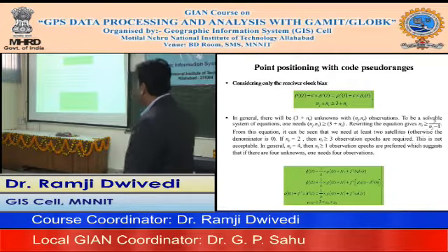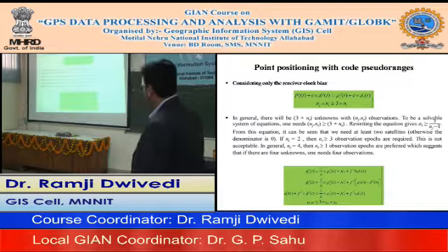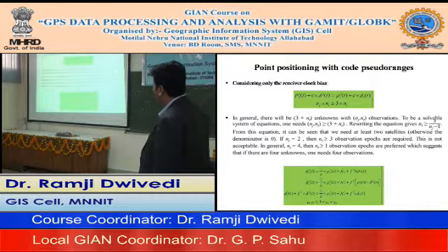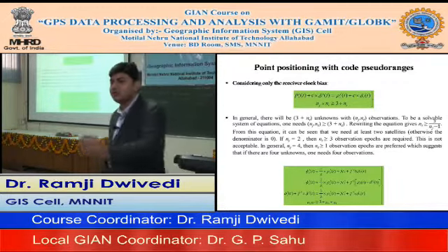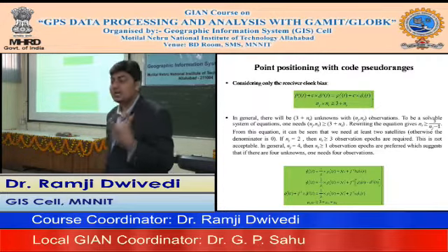So again, the discussion is about how the epoch relationship with respect to the number of satellites is relevant. So you could see here, what if you have just the minimum number of satellites, so that eventually this doesn't become 0, that Nj is equal to 2. So what will happen if you put Nj equal to 2? Eventually you have to take 3 epoch observations from those 2 satellites, isn't it?